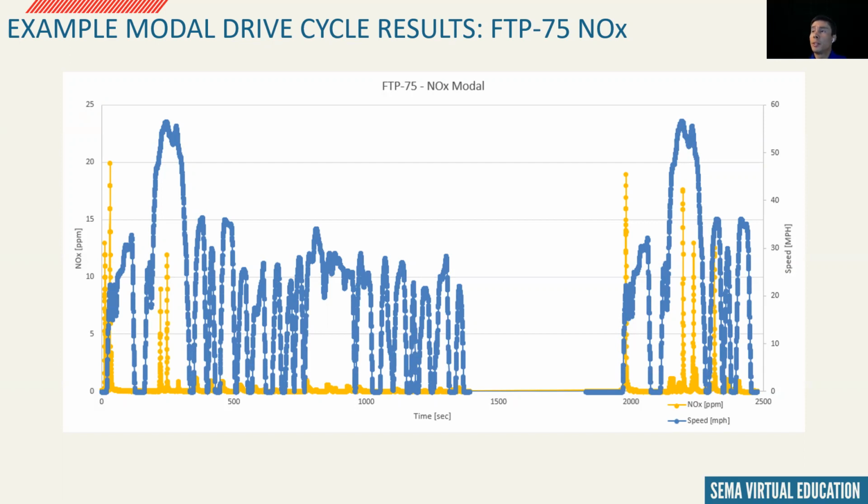Cam phasing is also something we should consider while working with NOx. The relationship of intake valve opening and exhaust valve closing overlap could induce EGR. EGR will reduce NOx. Having too much EGR will create unstable combustion though, so we want to be careful. Phasing exhaust valve closing after TDC will cause residual exhaust gases to remain in the cylinder at the start of the intake stroke.